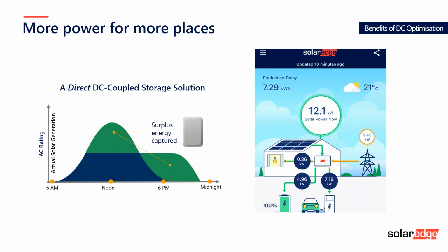So it's a cool, sunny spring morning in Sydney. You've got a car charging at full power on the AC side. You've got a depleted battery that's charging fully in the morning, and there's some loads in the home as well. And overall, we're seeing the system actually generating more power. So a couple of things are going on: the AC and DC sides aren't competing, so the battery is getting its full level of energy that it needs to charge quickly.